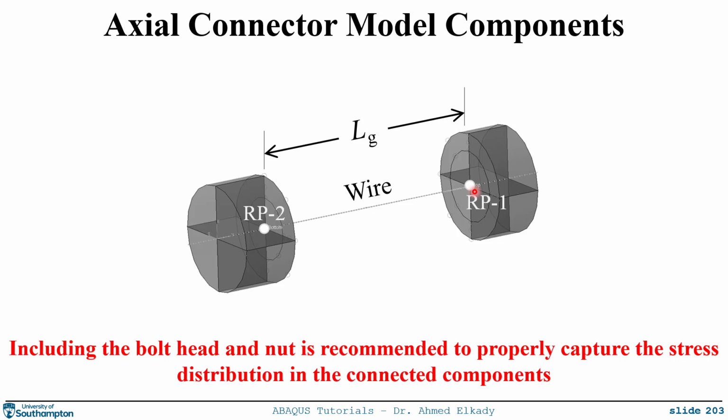And then you are going to connect these reference points together using a wire element. And this wire element will be assigned the force elongation behavior. The distance between the nut and the head represents your grip length or the total thickness of your connected components.